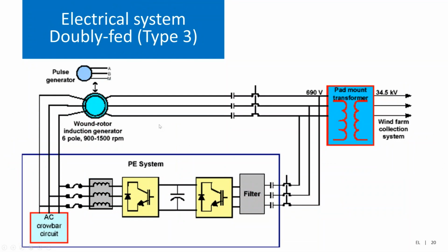I'm not going to go through this in detail because the point I want to make is that there's lots of ways to design a power electronic system that enable you to do what you want to do, which is to control your torque, the torque that the generator is extracting from the rotor. And you need to design this carefully and think about it carefully because it's one of the two parameters that you can control. You can control torque and you can control pitch as well as the design. And you have to figure out how to do this in a way that enables you to control that torque accurately, quickly, and reliably.